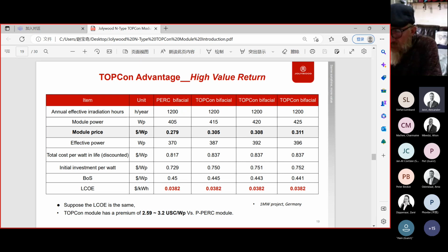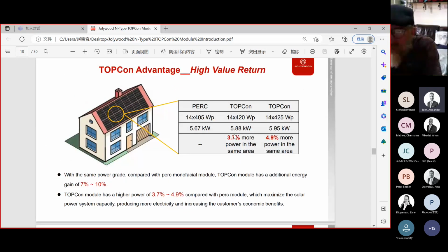The efficiency is still higher than on PERC, but on a direct roof mounted system you're obviously not going to get the extra bifacial add-on power production, because you don't have as much reflection as you would get on a ground mount system. So in general, bifacial panels give that extra 3 to 5%, what you see in the picture here on the presentation, but this is only the top side, only the front of the module.